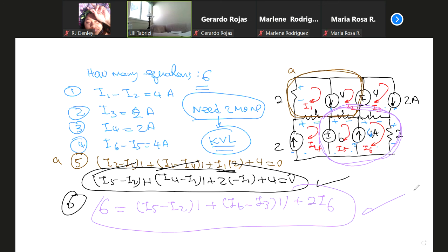But notice that I3 is not an unknown, it's equal to 2 amp. You plug in. I4 is 2 amp, plug in. You actually get the same as nodal, 4 equations, 4 unknowns. But 2 equations are 2 simple equations and 2 are a little bit longer. Pretty much you get the same result as nodal. But observation is easier than nodal, but same as nodal.